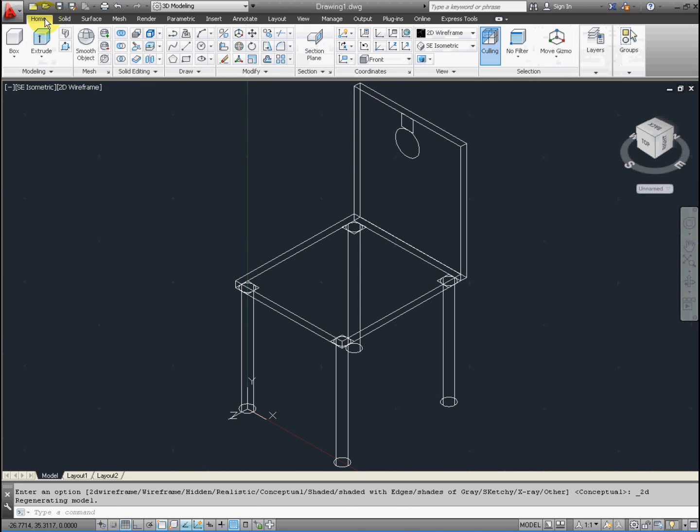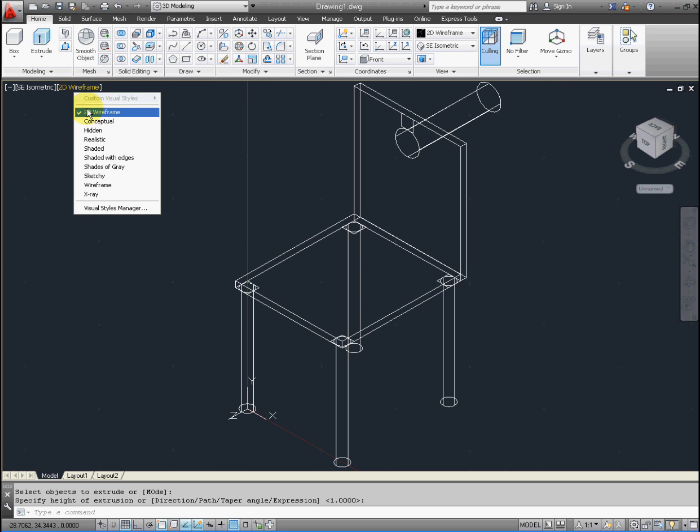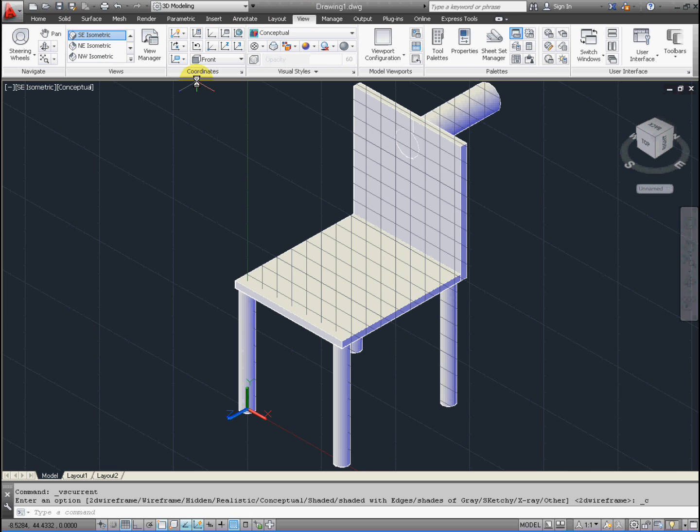And so what we're going to do is extrude that circle that we've created. So I'll just go ahead and type on the command line, extrude, and I'll select the circle, similar to how I did the back of the chair and the seat, and I want to move it through the back. So if for some reason your circle is not on the front, you'd move it the other way, but we want to make sure that it goes through the back of the chair. And you want to inspect this. If it doesn't go through, it will not work. We're actually going to be taking that out.